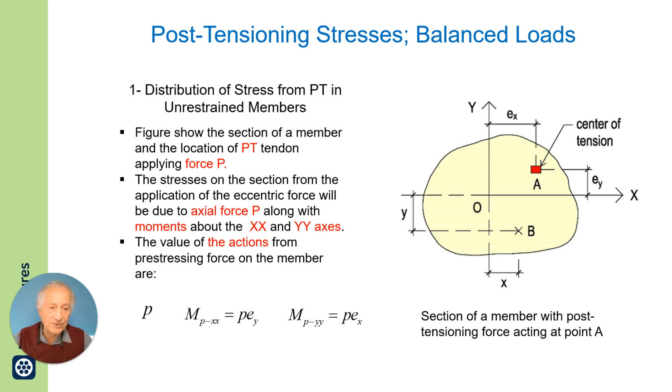The precompression is where it is, the tendon is stressed and anchored. At a cross-section along the length of a tendon, like the one I am showing here, it is only the friction between the tendon and its sheathing that is transferred to the section. This is the reality.